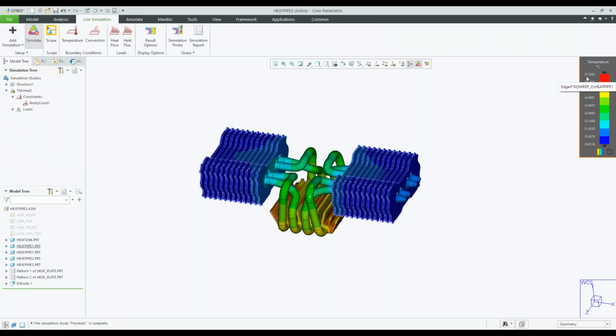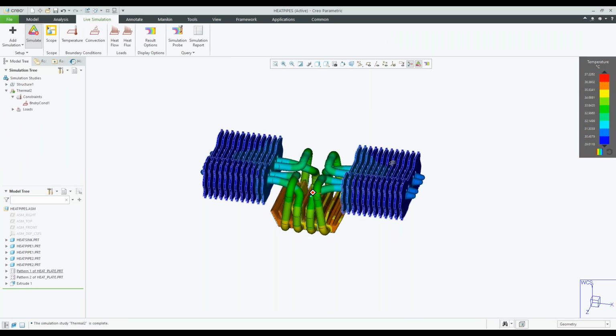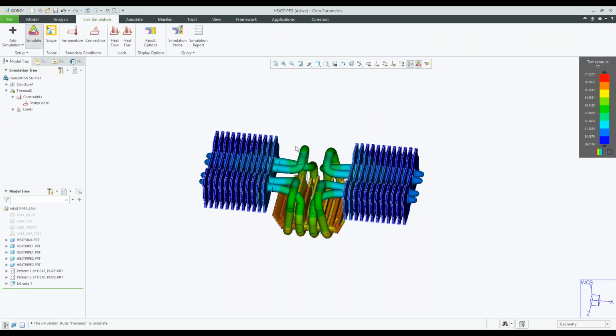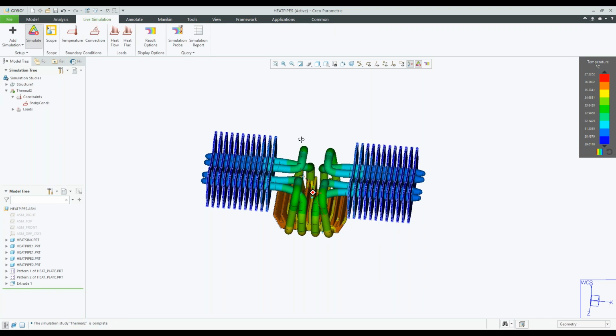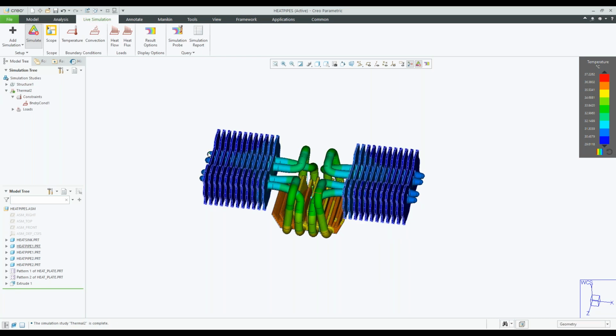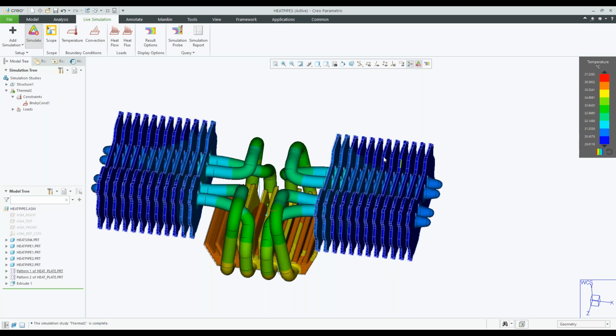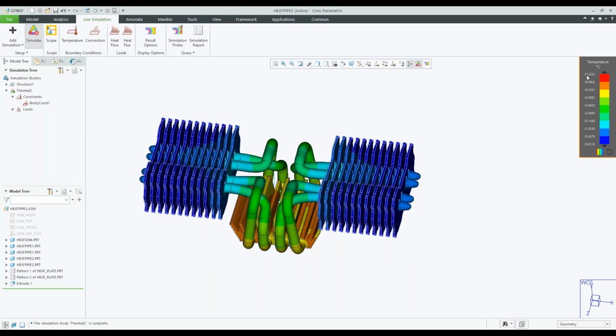That's it. Okay, so we took off what, 57 to 49? So we took off 8 millimeters. We reduced this by 16 millimeters in total, and we are still in our design range. All using Simulate Live, quick and easy. You get that feedback, and you can change your design.